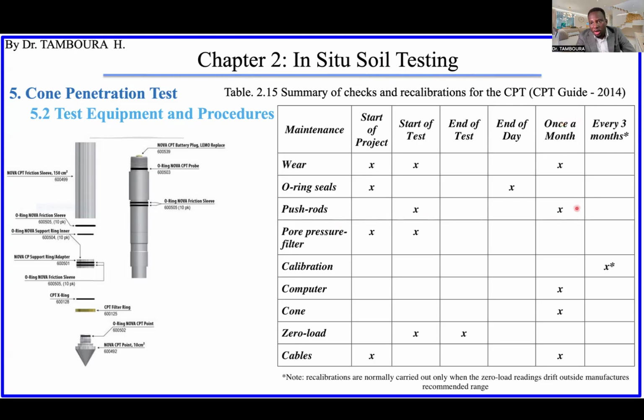Also check them once a month if you are using them permanently. The pore pressure filter, this one here: check it at the beginning of your project and at the start of the test.